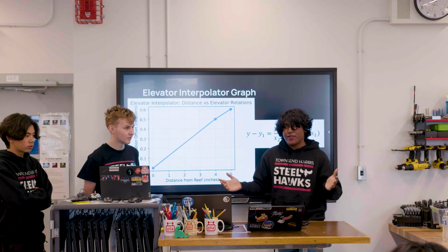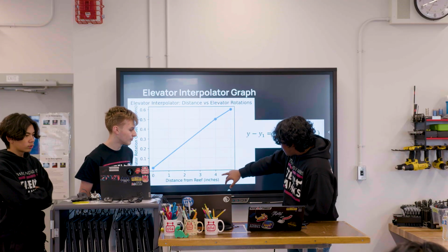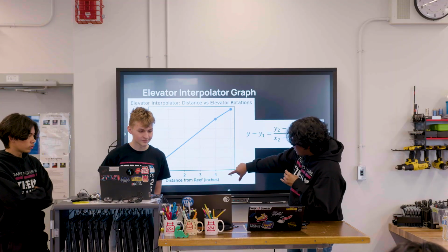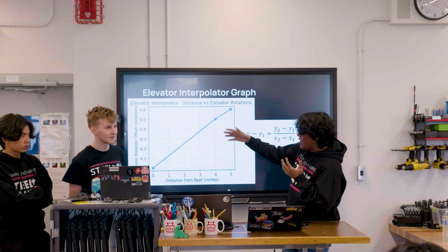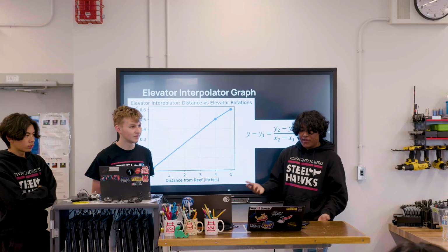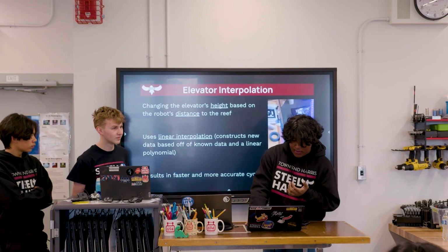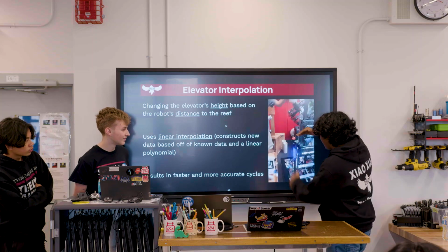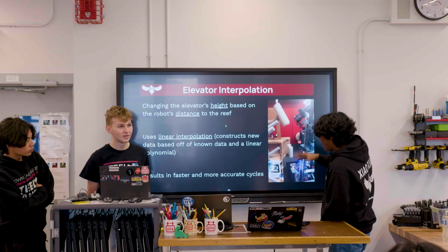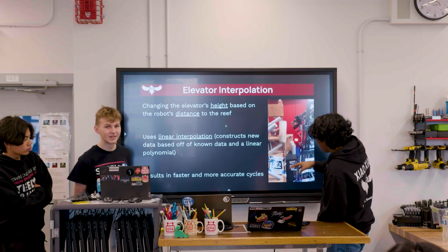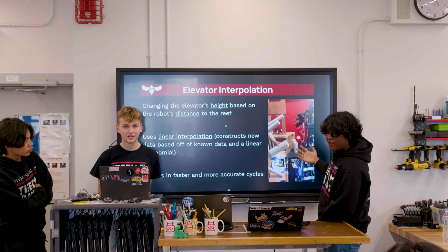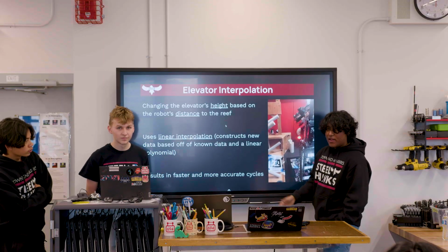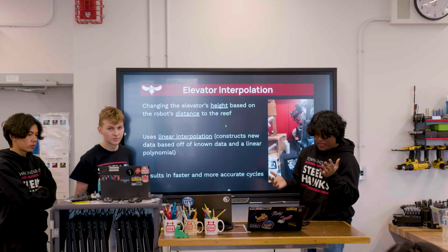Yeah, so you don't add an offset. But our next point that we found is when we're 4 inches away, and when we're 4 inches away, we add 0.5 rotations to that offset. So if we go back to this video, let's say when we're 4 inches away, your default, your constant set point when you're here, you're basically adding 0.5 rotations to your set point when you're 4 inches away. So that's really what I'm trying to get at.